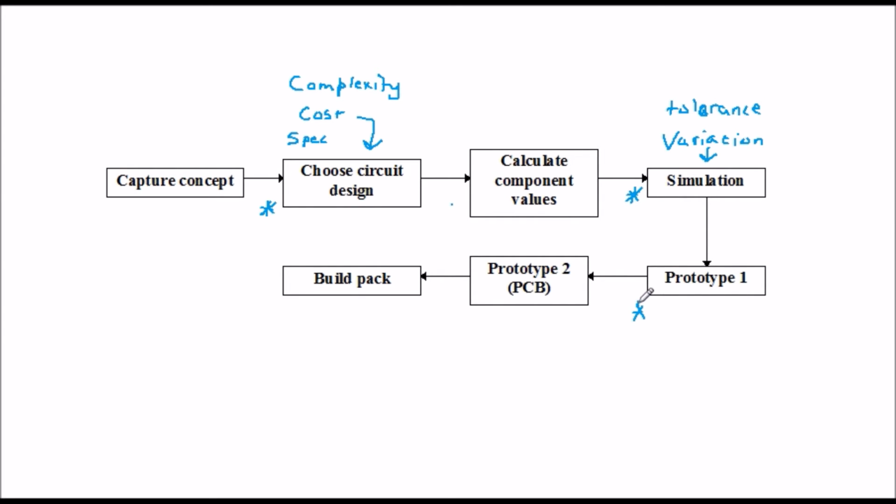This is basically the building of a test circuit to see if the design works. There are various ways of doing this, and I will illustrate some of them in the following videos. This test circuit can then be thoroughly checked out and all the voltages and other parameters measured to ensure that they are what are expected or within tolerance. It can also be tested with different signals and component types and values, again to check its stability and its robustness. A second prototype is often made to test the final manufacturing layout using the design of printed circuit board which will actually be manufactured or made.